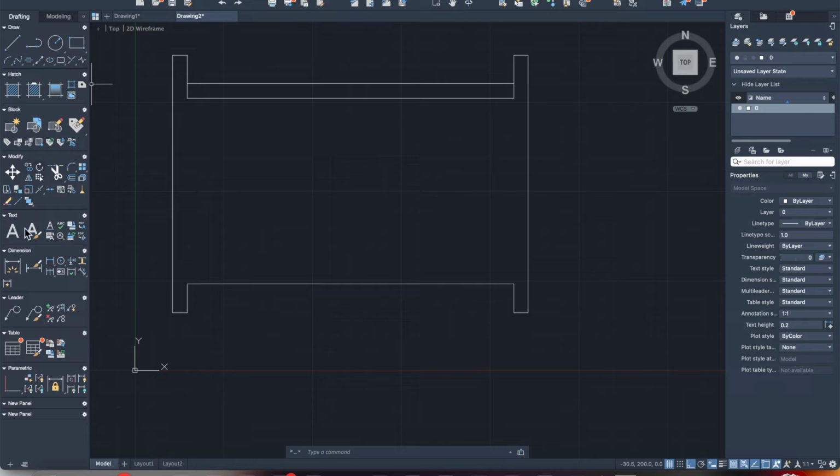And then you can simply trim it using, on a Mac, they look like scissors, the trim tool, and clean up the edges that way. So we grab the polyline tool, we repeat this step, up 10, across 230, and down 10. Spacebar, and trim.